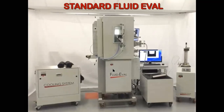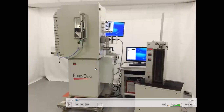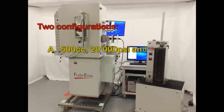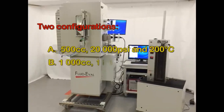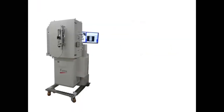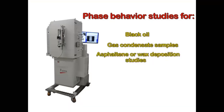This device is a mercury-free PVT and flow assurance system. When you go for your master's, you will definitely see it in other places. There are two possible configurations: 500 cc, 20,000 psi, and 200 degrees Celsius; 1,000 cc, 15,000 psi, and 200 degrees Celsius. The PVT system can perform phase behavior studies for black oil. The phase behavior diagram that I showed you, the data for that one actually comes from this kind of equipment. It also handles gas condensate samples, and asphaltene or wax deposition studies.